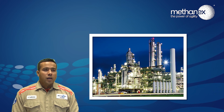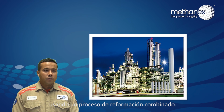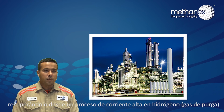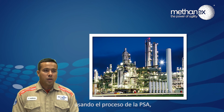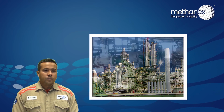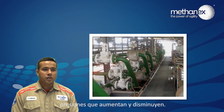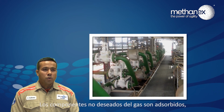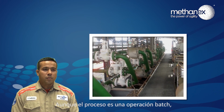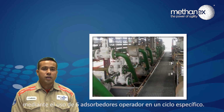PSA product uses. Hydrogen required for the methanol process is obtained by generating it using a combined reforming process. Extra hydrogen is therefore obtained by recovering it from a hydrogen-rich process stream or purge gas using the pressure swing adsorption process, which would otherwise be only used as a source of fuel. The pressure swing adsorption unit operates with alternating pressure increases and decreases. Unwanted components of the gas are adsorbed, leaving a product gas with the constituent wanted in the required concentration. Although the process is a batch operation, continuous product and off-gas flows are achieved by using 6 adsorbers operated in a specific cycle.